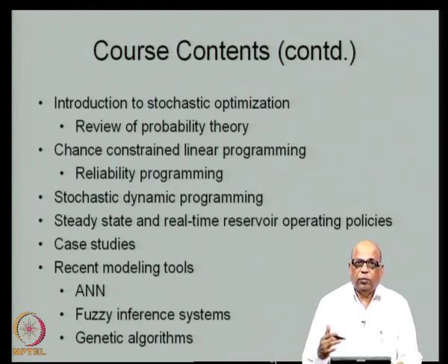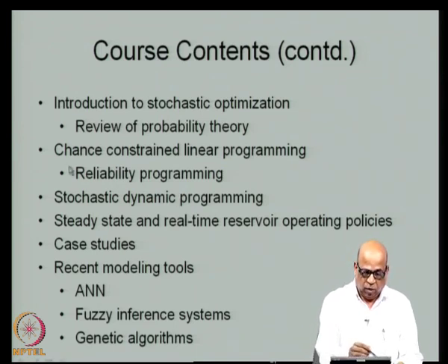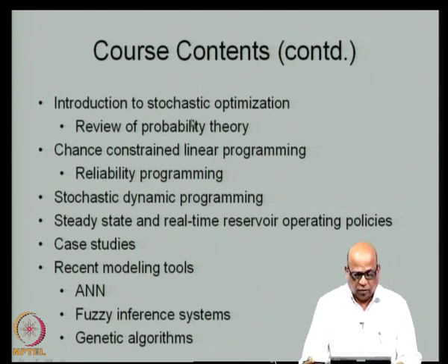The applications of these we will discuss with steady state and real time reservoir operating policies, which means what we obtain out of these stochastic optimization techniques may be essentially for long term steady state operating policies for reservoir systems. How we use these steady state long term operating policies for real time operation, that means day to day operation